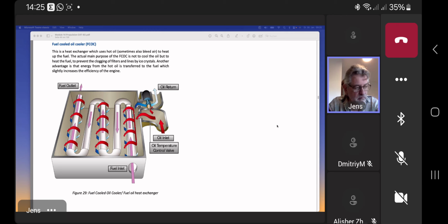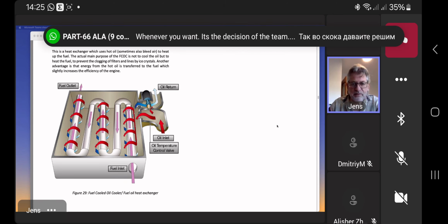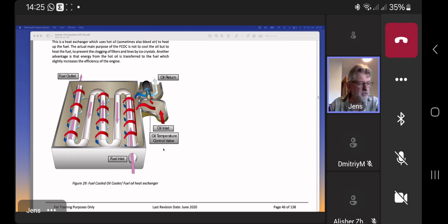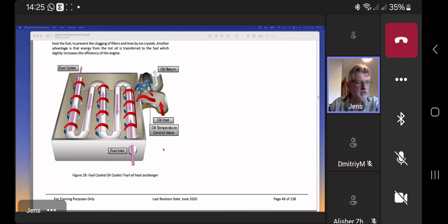it will influence the oil, I'm missing the word now, I'm sorry. So it may change the behavior of the oil, so the oil cannot lubricate anymore, and then we have a very fast failure of the bearings, which can be not so nice and very expensive. So oil pressure here is slightly higher than the fuel pressure in our fuel oil heat exchanger.